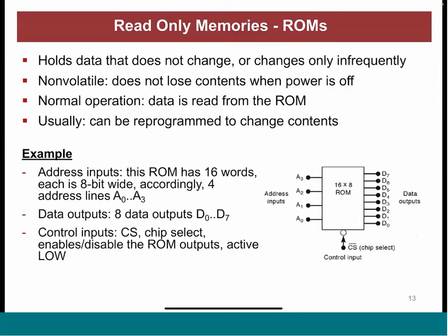No need for a read-write pin, right? So there is no need for this pin, because it's always a read operation. And there is no need for data in, because I don't write, I just read. So I need just data out. This is why for ROMs we have just the address bus.